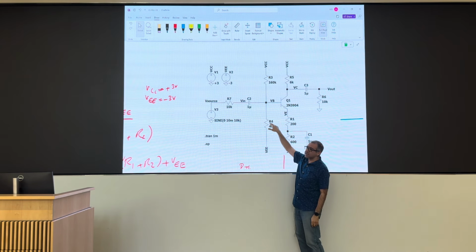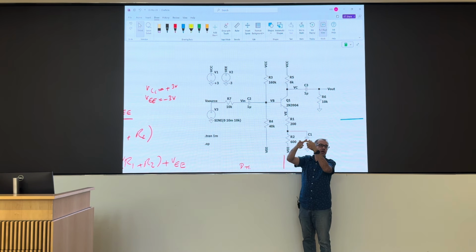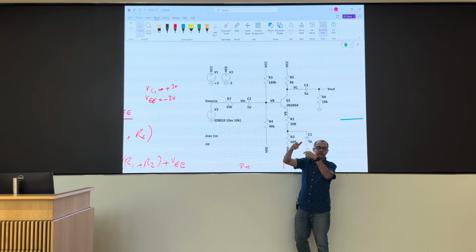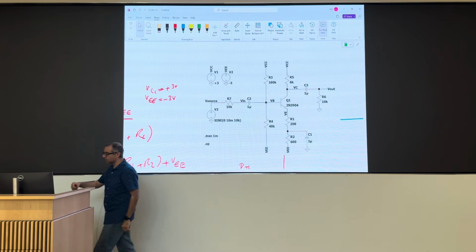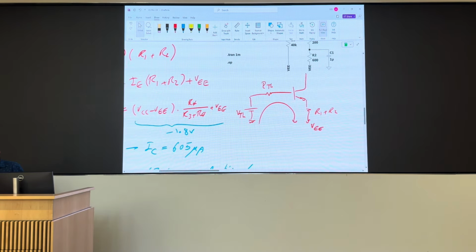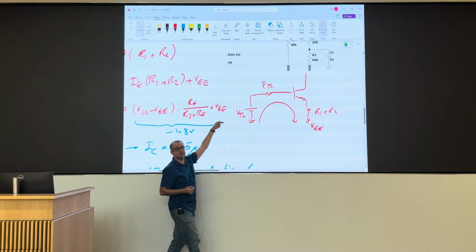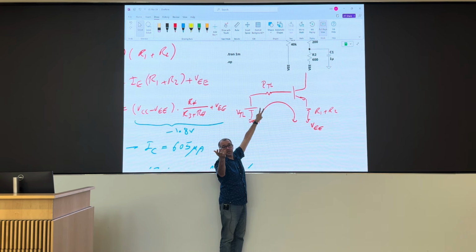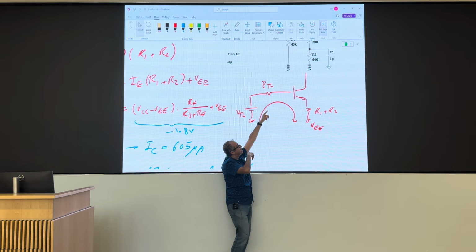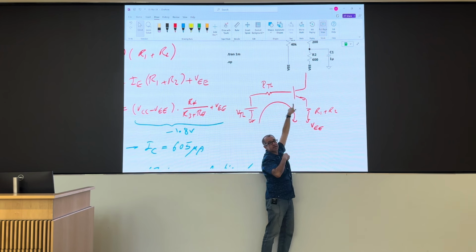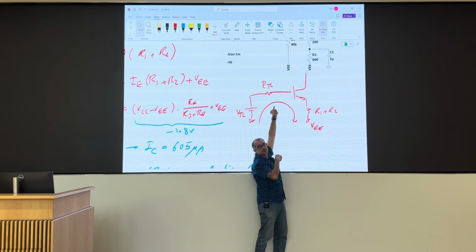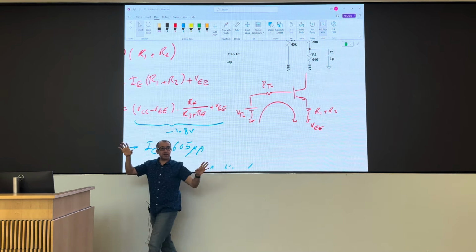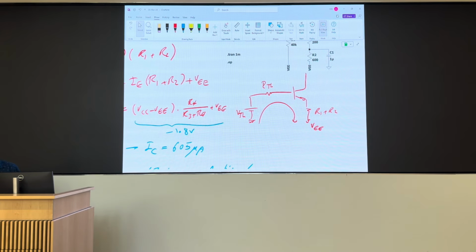But with a larger resistor, I would get a little bit more voltage drop across that resistor in my Thevenin circuit, right? That voltage drop will go up a little bit, but it's not a lot of voltage because the current is small. It's a base current, right? So the Thevenin resistance will be 10 times larger if I use 10 times larger resistors for R3 and R4. But this voltage dominates. So the changes here do not affect your IC that much, right? So in terms of biasing, I could do it with all of those combinations.